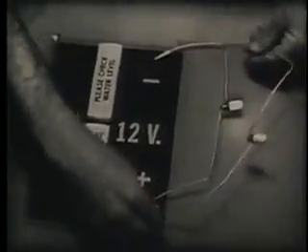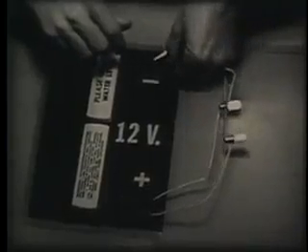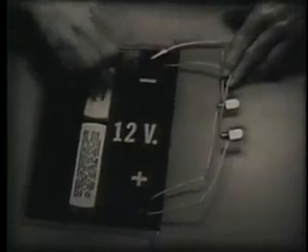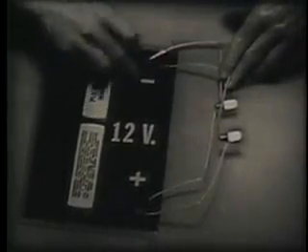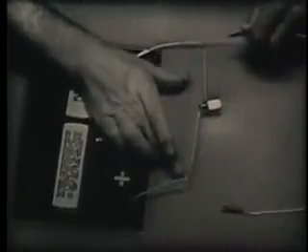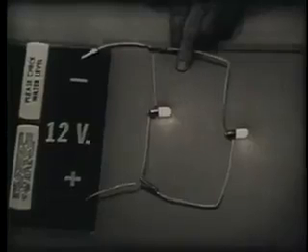If I move this light over here like this, I have exactly the same circuit. The total voltage still appears across each branch. Now, since the applied voltage is felt across this bulb, I should be able to connect this one like this and still have the applied voltage across it. And you can see that it's starting to look like a parallel circuit.